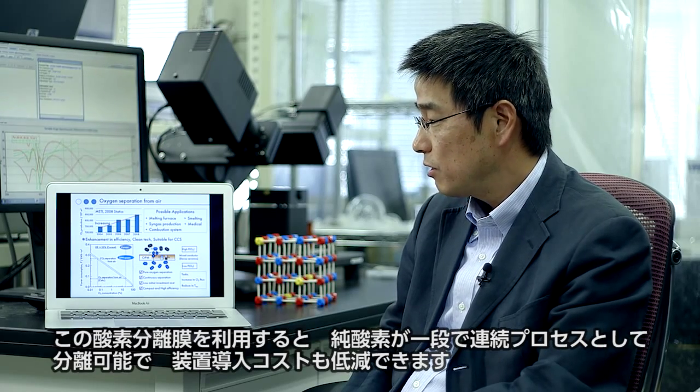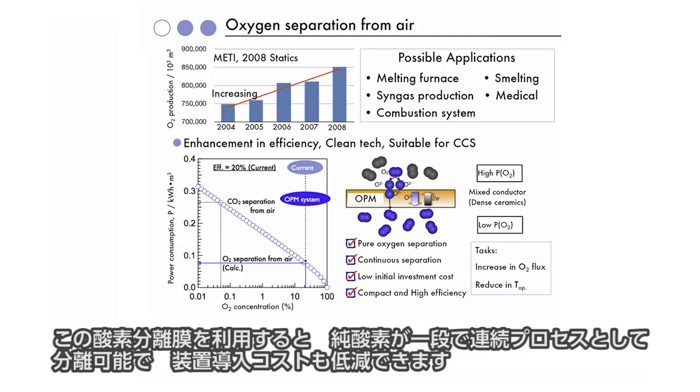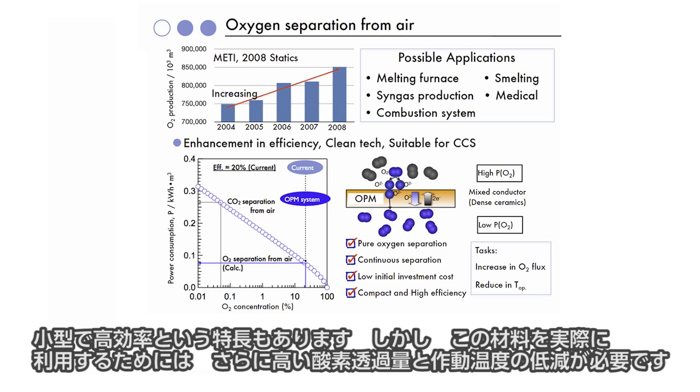So by using this oxygen permeation membrane, pure oxygen can be separated in one stage, and this is a continuous separation process, so initial investment cost can be much reduced. And it brings us the advantage of compactness and high efficiency.